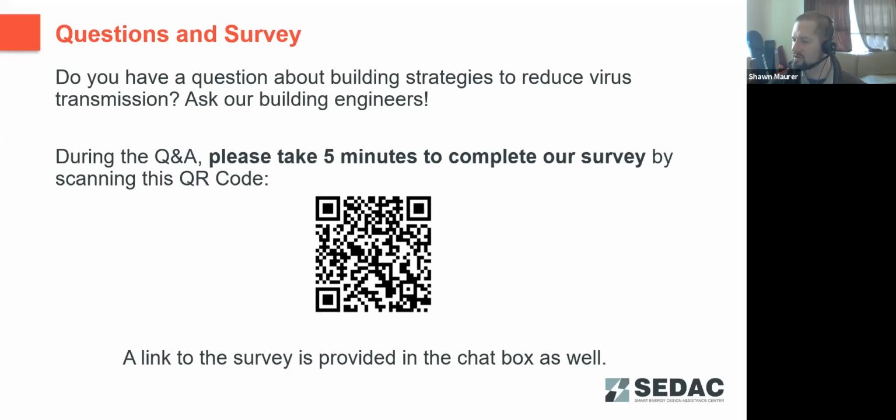There was another question on if your building is negative due to multiple fume hoods, like a laboratory classroom building. Your building is drawing in outside air through walls, gaps, and leaks. Typically, if you've got a building that's negative, there is some design issue there.